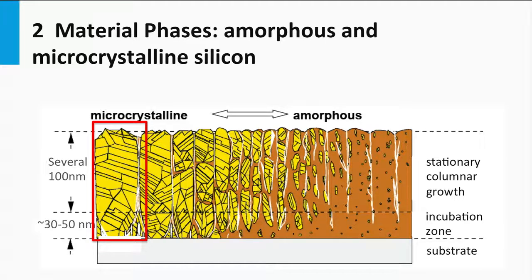Going from right to left, the amorphous phase is changing into a mixed phase with a few small crystalline grains to a phase which is dominated by large crystalline grains and a small fraction of amorphous tissue. The best nanocrystalline silicon bulk materials used in solar cells have a network close to the so-called amorphous to nanocrystalline silicon transition, and its crystalline volume fraction is in the order of 60%.